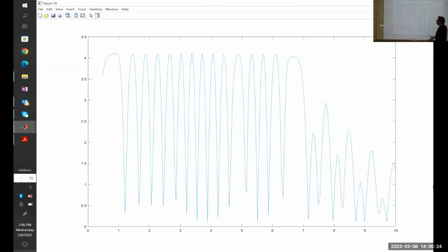In any system, due to practical reasons, we're not going to let this current be that high for so long. So this is a situation we will never allow. A protection scheme typically will try to clear a fault in a matter of a few cycles, like 5 cycles maybe of the signal. We're talking something less than 100 milliseconds.